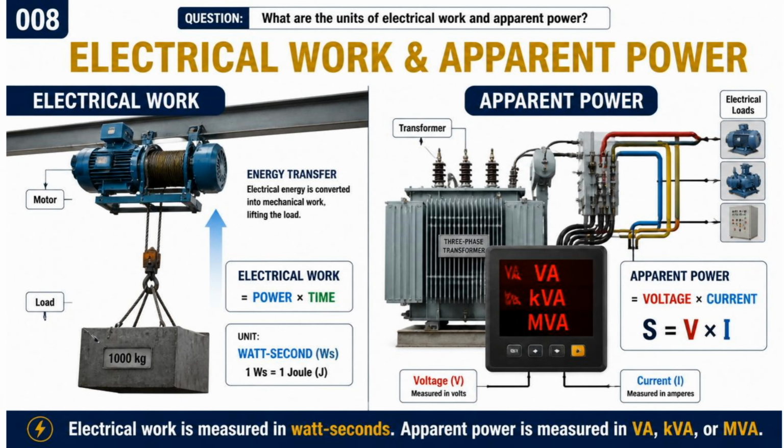Question 8. What is the unit of electrical work, and what is the unit of apparent power? The unit of electrical work is the watt-second, which represents the amount of electrical energy used or produced over a period of time. The unit of apparent power is the volt-ampere, abbreviated as VA. For larger power systems, apparent power is commonly expressed in kilovolt-amperes, or kVA, and megavolt-amperes, or MVA. Apparent power represents the total power supplied in an AC electrical system, before considering the effects of the power factor.